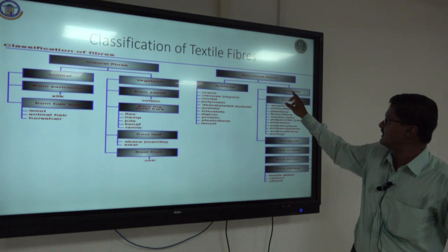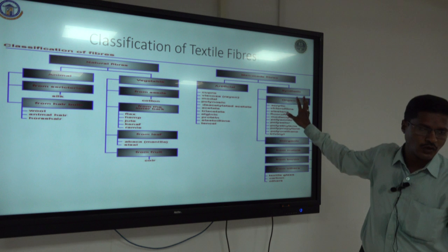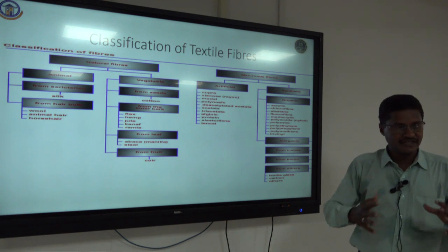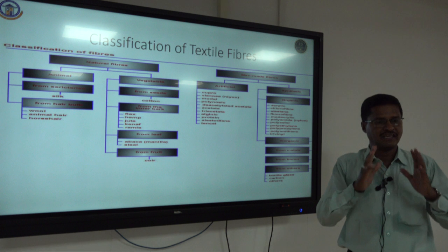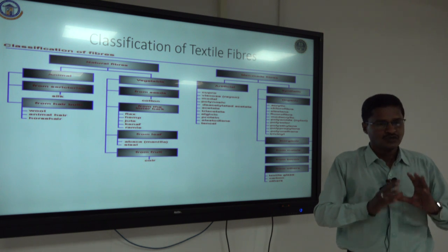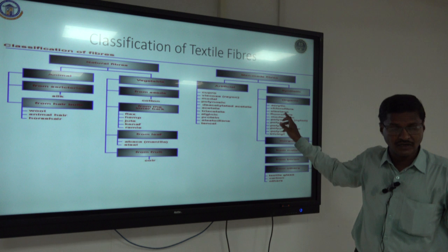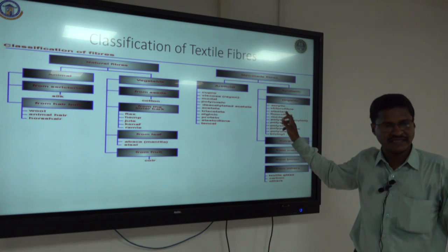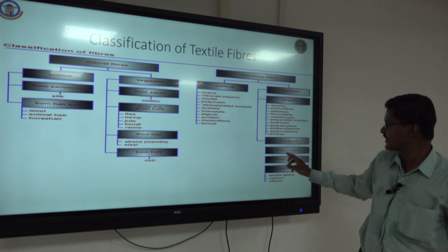Next, another type of fiber is synthetic fiber. That is the organic fiber. Organic fiber is again classified into acrylic fiber, polyamide fiber, polyester fiber, polyvinyl alcohol and polyvinyl acetate, like different types of synthetic fiber. 100% of the fiber is chemical. We cannot use even 0.1% natural material or artificial material, so we use the synthetic chemical 100%. So it is not biodegradable, and also it is not eco-friendly. It will be used blended, or as a composite material for manufacturing plastics, polymers and other materials.